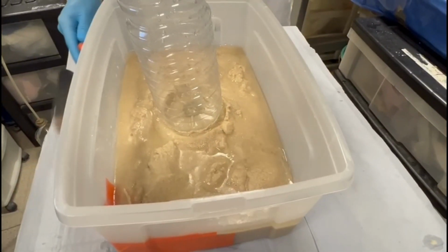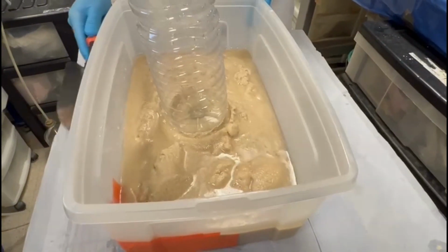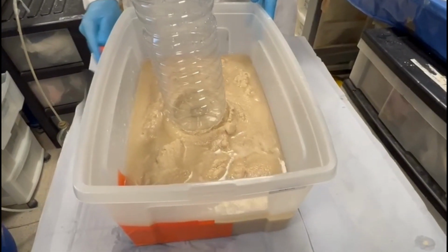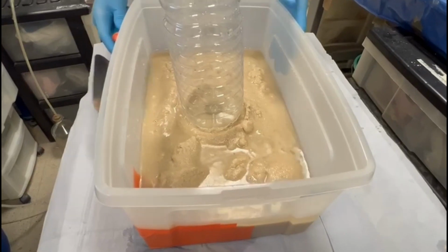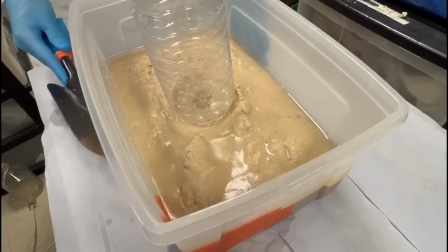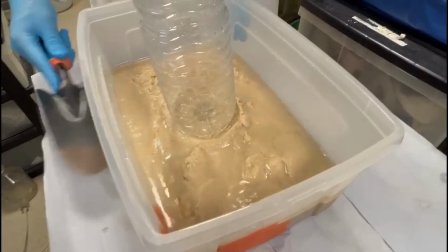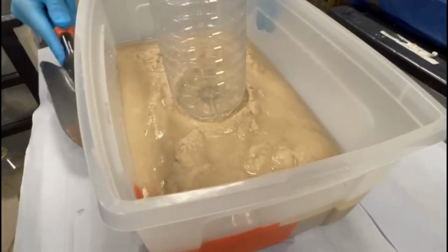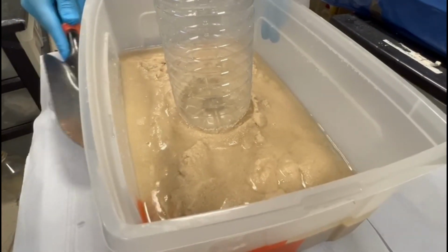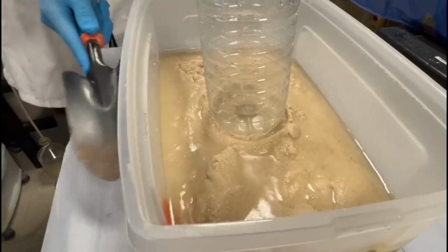You can see here that the building starts to tilt with respect to its initial state. This is because we had in the beginning a small difference in the saturation degree inside the sand around the building, and this caused one part of the sand to liquefy before the other, which led to this tilt.